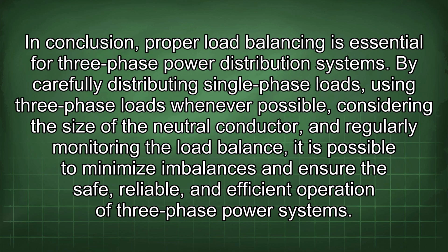In conclusion, proper load balancing is essential for three-phase power distribution systems. By carefully distributing single-phase loads, using three-phase loads whenever possible, considering the size of the neutral conductor, and regularly monitoring the load balance, it is possible to minimize imbalances and ensure the safe, reliable, and efficient operation of three-phase power systems.